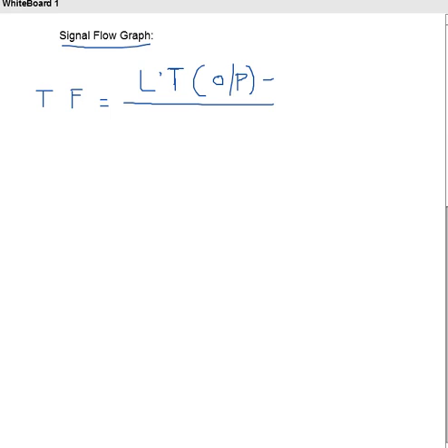Suppose, for example, I am naming the Laplace transform of output as C. So you have to write the Laplace transform of output as C of S. S is nothing but the Laplace variable, the S domain. The output I represented is capital C. And this is the definition of transfer function. I just wrote output as OP, input as IP. So the Laplace transform of input.